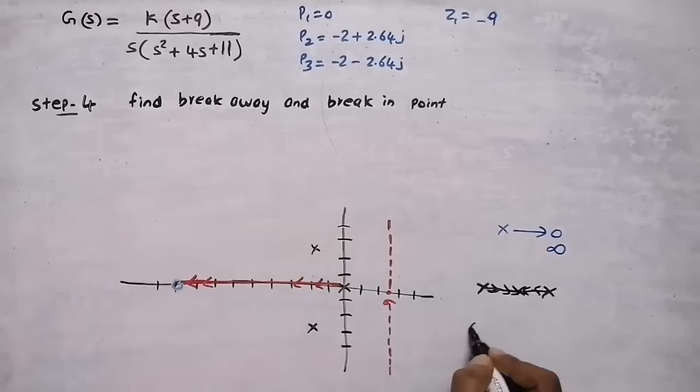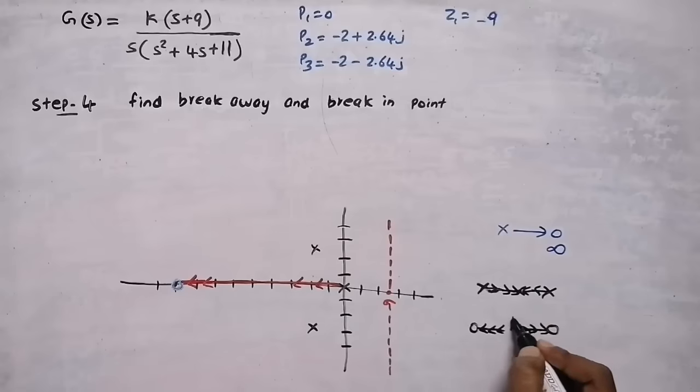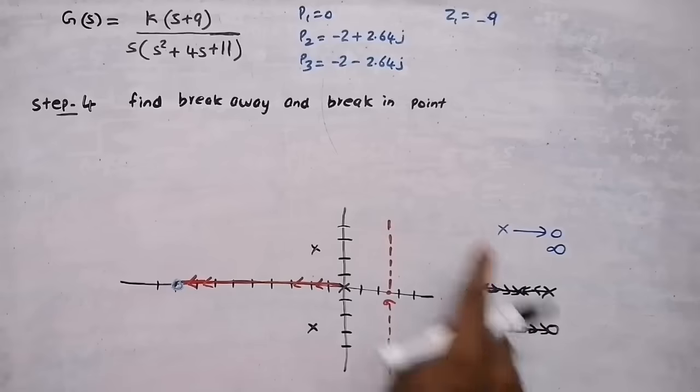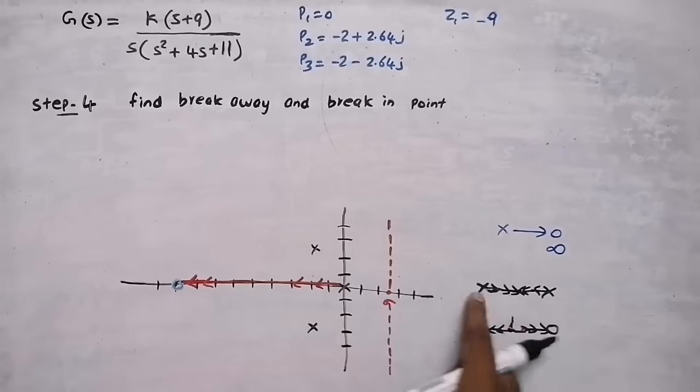With zeros, the root locus will start from a pole and it will end at 0. The root locus will come from somewhere and at a point it will break in, and end at the zeros on this side and this side. So there will be a break-in point. When there are adjacent zeros, there is a break-in point. When there are adjacent poles, there is a breakaway point.